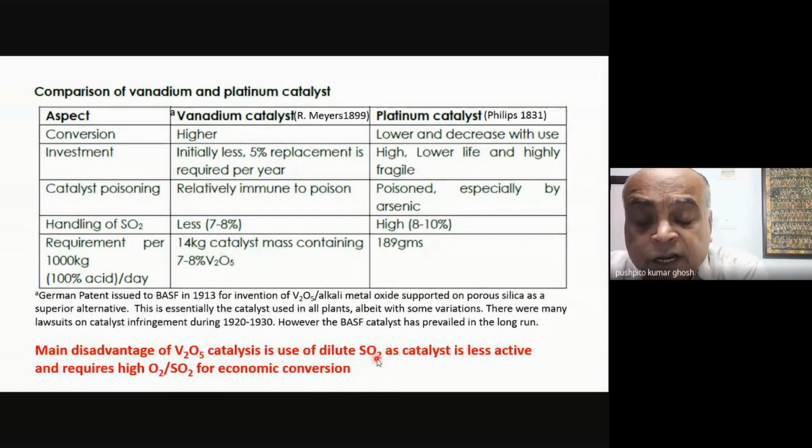That's the reason why I have to take a lower concentration of SO2 and make sure that I've got more than enough oxygen, so that even after the consumption of oxygen, I still have a sufficient amount of oxygen left. Because if I just take stoichiometric amounts, I have had it, because my oxygen levels will fall off very fast. Is that clear?